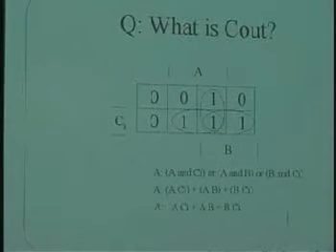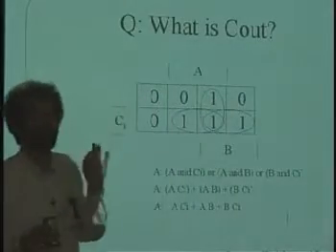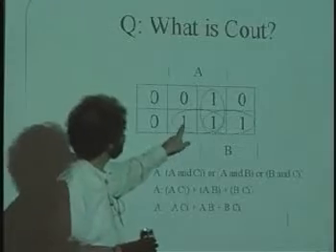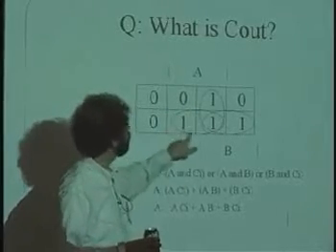So that's nice. But it turns out that we can do a simplification on this K-map, which is identical to the very difficult simplifications that you guys did in the discrete math course. We can make these circles bigger than one square. What we can do in particular is I can take these two ones that are near each other that used to have a circle on each one, and I can circle both of them.